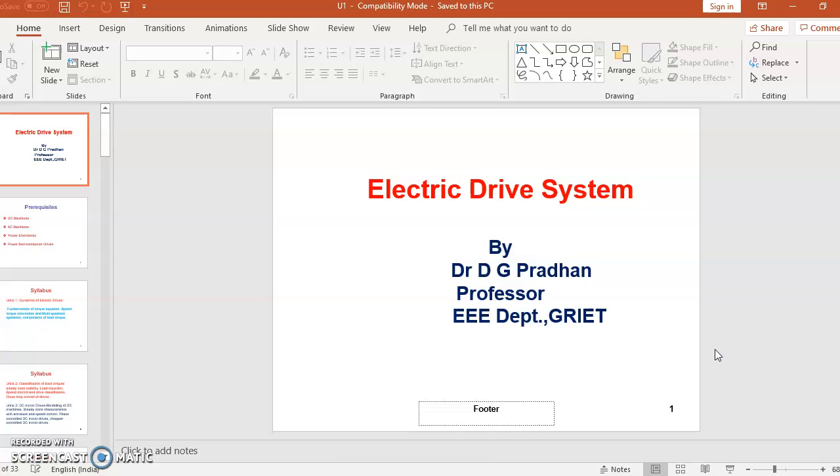Generally DC machines are used for adjustable speed drives as well as constant speed drives, position control drives, and control of motor drives below and above the rated speed. The methods of control of DC motor drives are simpler in design and less expensive when compared to other motor drives, and provide very good speed regulation with steady state, starting, braking and speed reversals, with a wide range of industrial applications such as those in paper mills, rolling mills, cranes, lifts, etc.